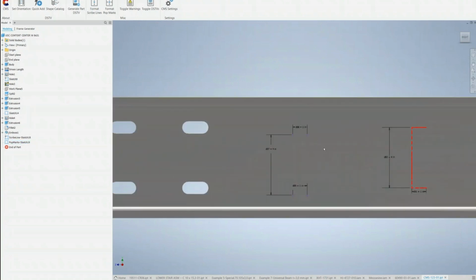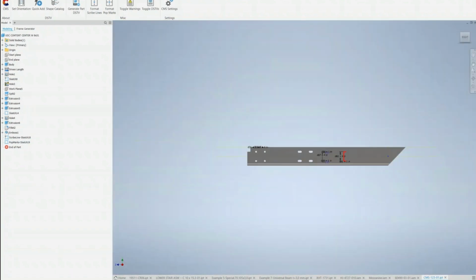Most of the time, you want to minimize your operation time. So instead of etching the whole lines, you put in a line for the start and end of this channel, so that your welder can come and weld the channel over here, as a rough example. If you want to bring those points as pop marks, you can also do that. You highlight them and format them as a pop mark, and the software will bring them as pop marks as well.